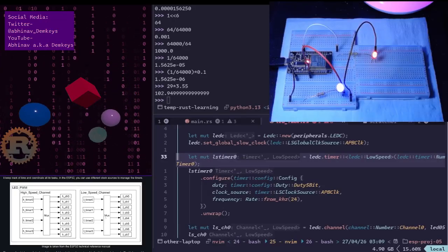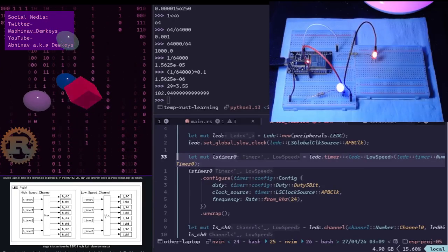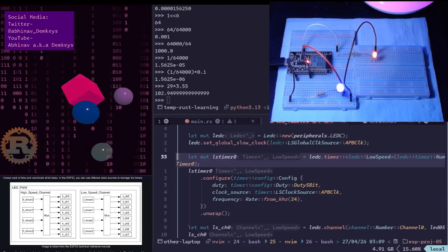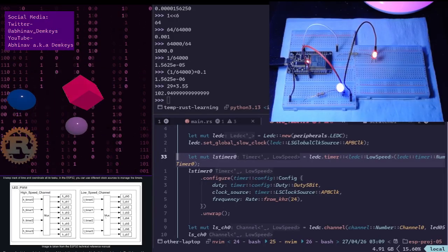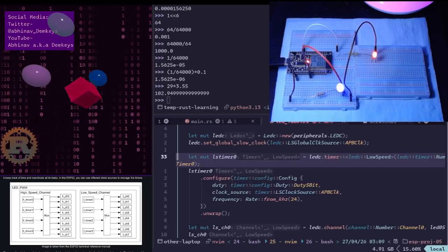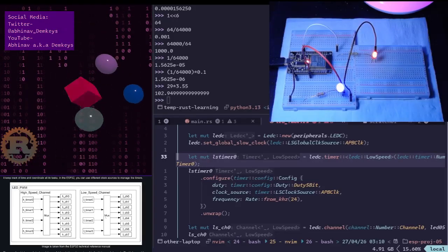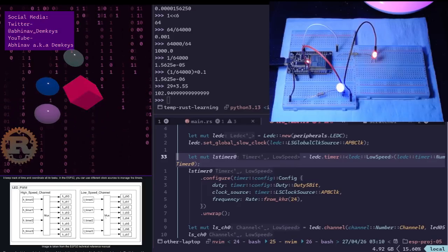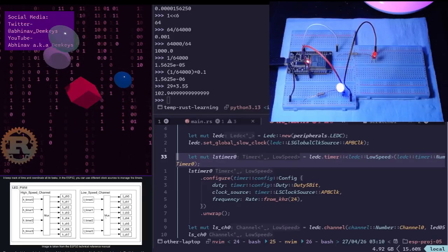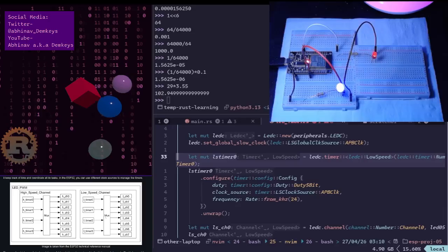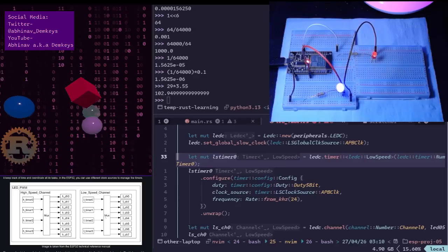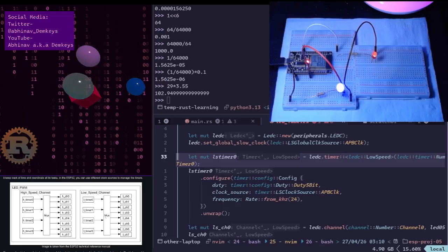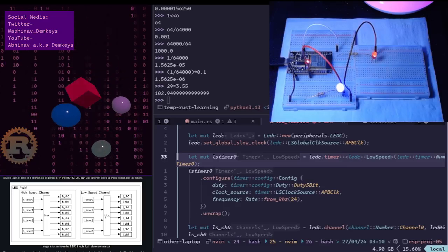Okay. And the other reason is HAL maturity. The ESP HAL is designed to be cross-chip compatible. Other chips in the ESP32 family might have 3 or 4 options in that same enum. To keep that code structure the same across all chips, the developers use an enum even if your specific chip only supports one stable option right now.